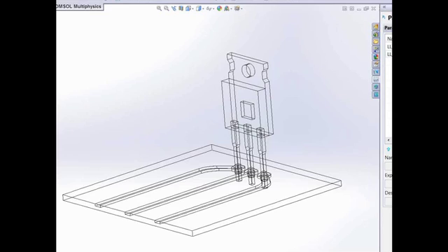And I could actually manually change the value here from 19 millimeters to say 22 millimeters. Let's see what happens. And now note that when I go back here to the live link node, I can see that there's a little sign here saying that this needs to be updated. And when I update this, what's happening is that the SolidWorks model is changed.